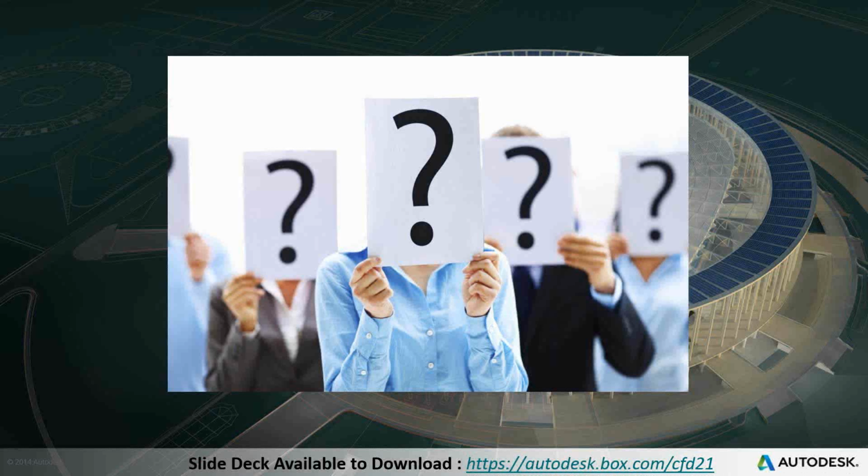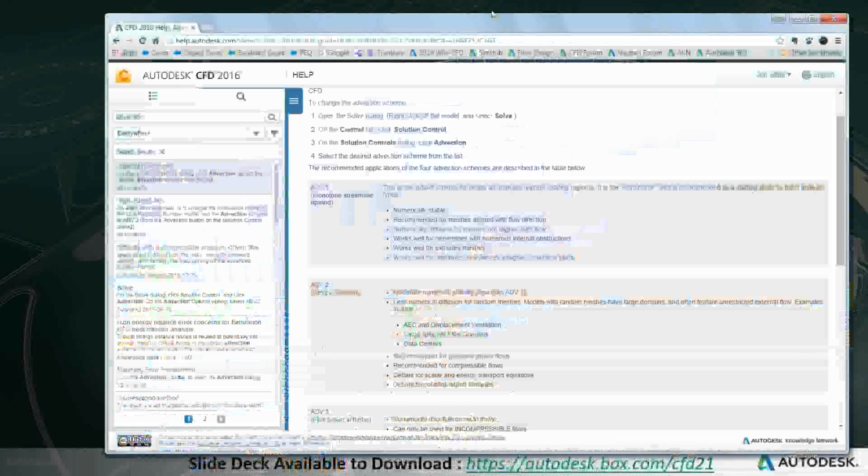It gets me every time when somebody's complaining about results without knowing that I did it, because it's an automatic click for me. But really, there are the times that you really need to do it, like when you're doing a free surface. I've seen some people need to use it for scalar analyses as well when you're really not having any of that scalar mixing, because it'll make it less diffusive. So it can help out in that scenario.